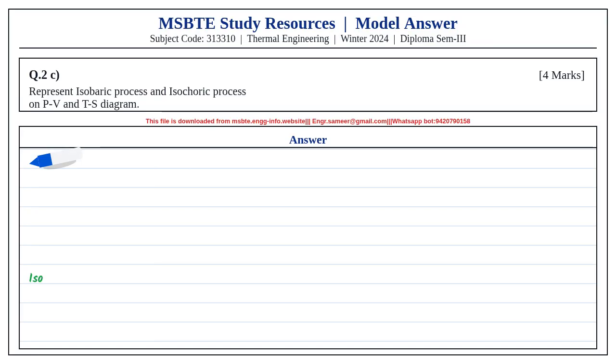Two-stroke engine gives 1 power stroke in every revolution, while four-stroke engine gives 1 power stroke in 2 revolutions. Two-stroke engine uses ports for inlet and exhaust, while four-stroke engine uses valves. Power output is higher in two-stroke for the same size, but four-stroke has comparatively lower power output. Fuel consumption is higher in two-stroke and lower in four-stroke.